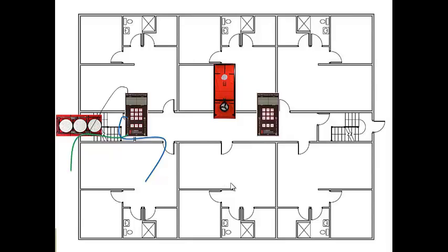Okay, so then we need to connect our channel B to our fan on our dwelling unit, our test unit. And then on this one, we're using that T connection. Remember, we need the fan pressure with respect to the space it's in, and we need to be measuring house with respect to building